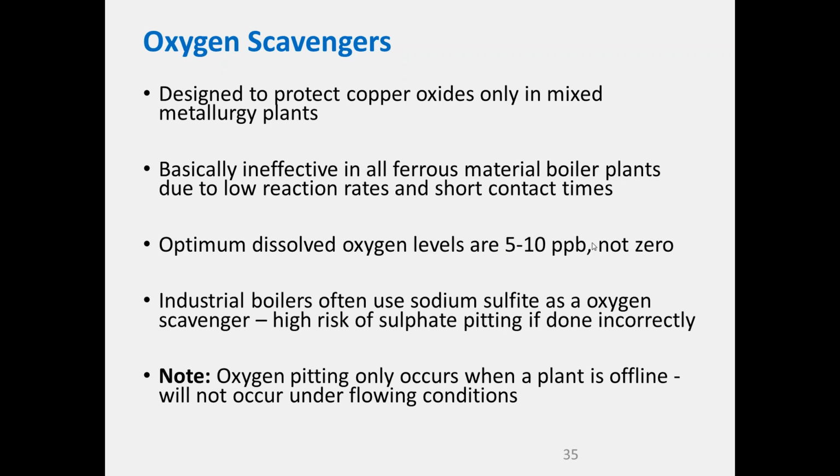Now what happens there is that if we have a little bit of oxygen present in the water, it helps with that protective oxide layer that wants to form. We end up with a little bit more hematite compared to magnetite, and that's a whole lot more protective.